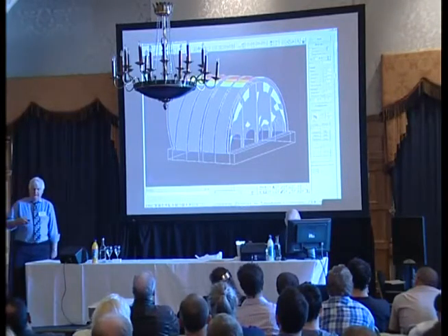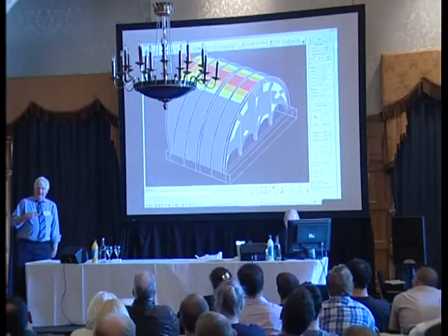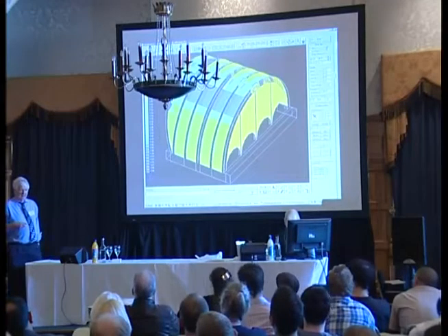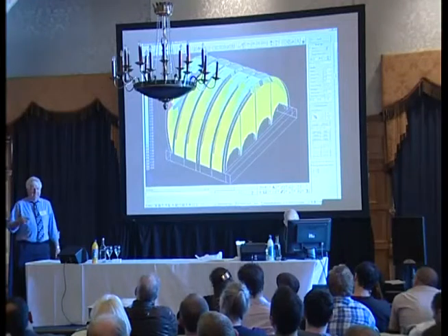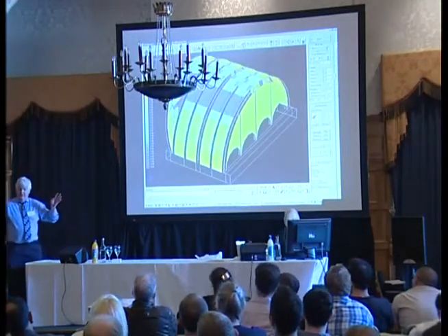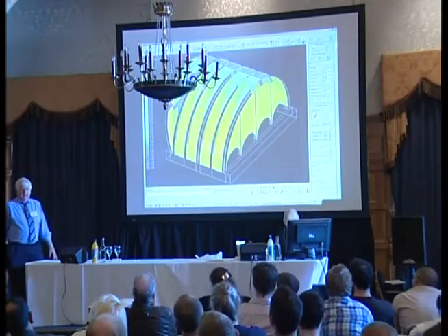In that latitude tent, I was very concerned about somebody leaning on the A-frame, which is balanced, holding the whole thing up. So I put a 2.5 ton load at the top of one of these A-frames to see what would happen. Nothing happened, surprisingly, but the load went, you can see the analysis. You see the wind loading changing. It solves each load case.